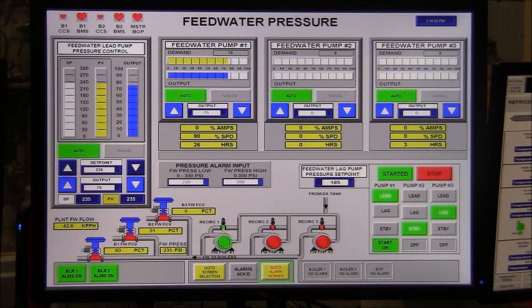At present, while this valve is indicating open and these two are indicating closed, the valves actually at this moment, 14th of February here, are disabled and they're manually cranked open to maintain recirc. And we probably have a little more recirc than we need, but this has not been fully commissioned yet. We had problems with one of these actuators. That's out for replacement.